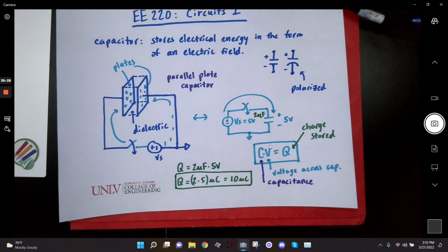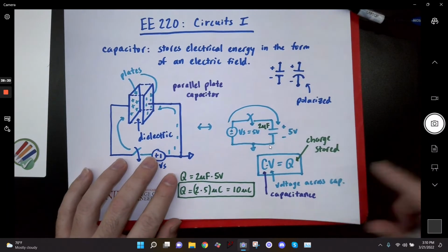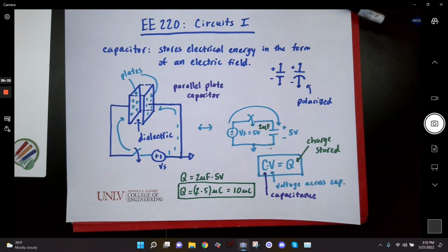Yeah, that's a good question. So first of all, in the video, he wasn't making a capacitor, he was making spark gaps, okay? And in that circuit, he had high voltage, but in order to get it to actually arc, you need a particular distance, because what happens when you get an arc, an electrical arc in real life, is you might have a really high voltage here and a really low voltage here, and the air around the two nodes becomes ionized, but that ionized air will only reach so far.